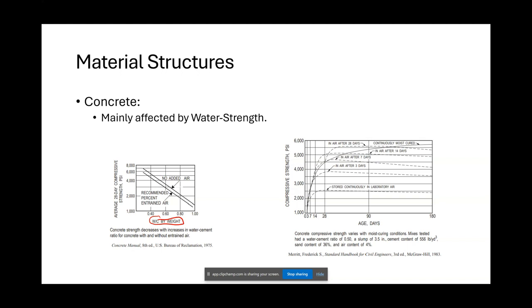And then you can see this chart over here that's relative to the age in days and the compressive strength. Everything's roughly after 3 days, 7 days, 28 days. You can see over time there's a pretty exponential difference right about here for most of them, and then this one up here takes a little bit more time to flatten out, but over 28 days they tend to even out.